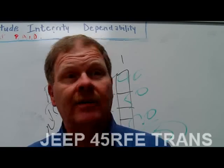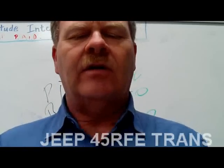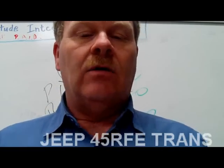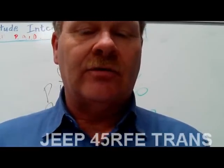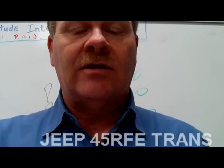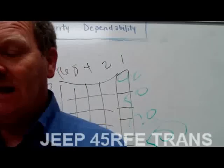Engine load tied directly to manifold pressure? Yeah. Engine vacuum drops with manifold, whenever you got more load, you got less vacuum. In other words, less vacuum equals more pressure, see? But the TCM uses manifold pressure reading as a factor in calculating torque and prevent grade hunting.